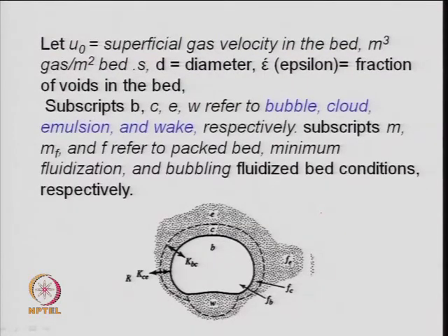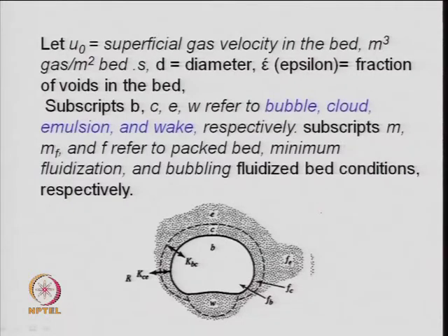So, just very briefly I will talk about the design concept, because the design of a fluidized bed reactor is a separate course where you understand the hydrodynamics, calculate all these hydrodynamic parameters, calculate the RTD model, right, using it to calculate the dispersion number and then correlate for the exit conversion. So, here I am very briefly talking about what are the parameters required to design a fluidized bed reactor when you use a catalyst, or what is the basic approach to design a fluidized bed reactor. So, I have just defined certain parameters here.